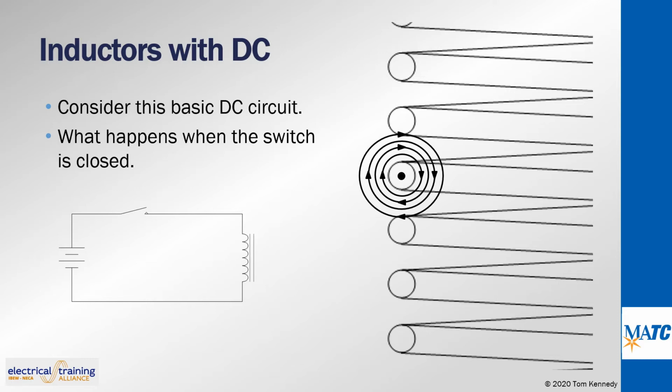the image. Since there is relative motion and a magnetic field in the conductor, a voltage is induced based on Faraday's law. Fleming's left-hand rule can be applied to the adjacent conductors to the conductor shown here. The polarity of the voltage that is induced into the coil is the opposite direction from the applied voltage. This creation of counter-electromotive force when a change in voltage occurs is known as inductance.